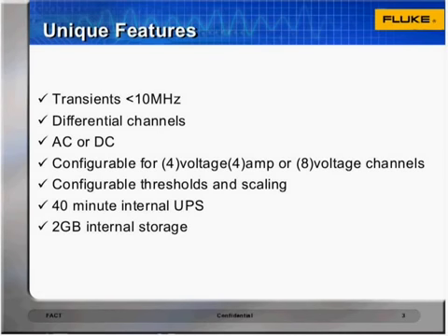Utilizing differential channels, you have the ability to do custom measurements outside of standard transformer configurations. Each channel can be a separate meter unto itself, including the ability to mix AC and DC signals. You can even go as far as using all 8 channels for voltage measurements, allowing for the ability to monitor 2 3-phase inputs. For example, the input and output of a voltage regulator or UPS.